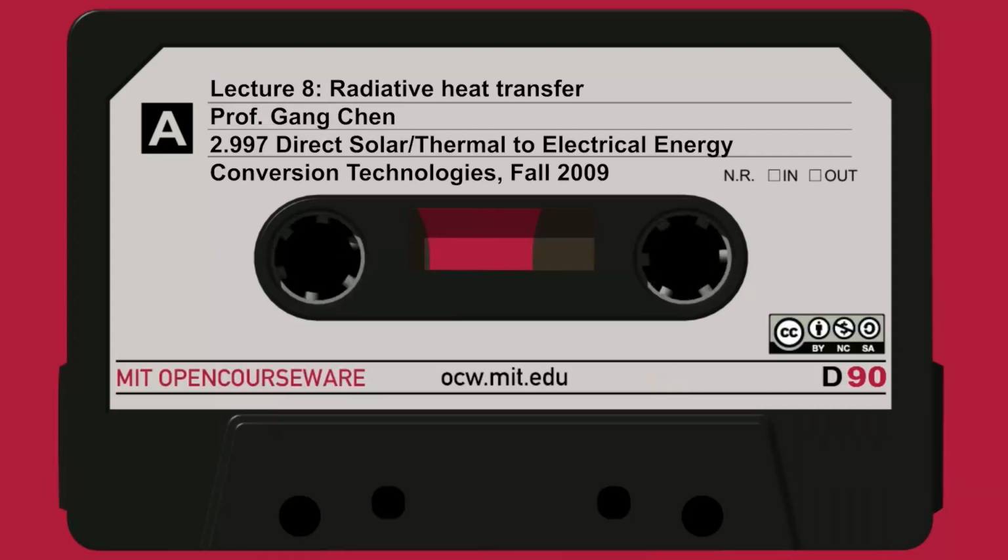So it's a matter of the band gap times the Carnot efficiency limit of the solar cell. The solar cell itself is operated at low temperature, so the Carnot efficiency limit is really from the sun temperature to the earth. If you do an infinite multi-junction solar cell, the maximum efficiency is still 85%, the same upper limit.